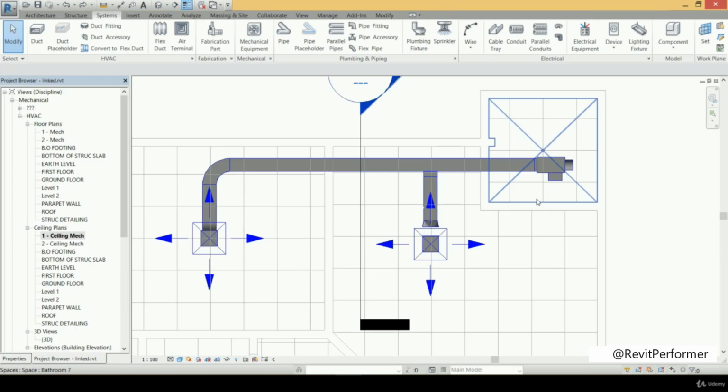But if there is a heat exchange between the air inside the duct and the air outside the duct or the surrounding air, in this condition, the supplying air will lose its conditioning temperature. So we need to insulate the outside surface of the metallic duct, and this is done with insulating material. And that outside surface insulation has a standard thickness to be, for example, 25 millimeter, which is about 1 inch. And this is in case the duct lays inside the building.